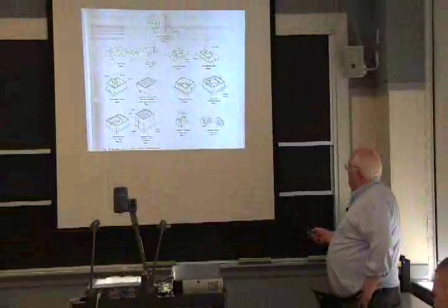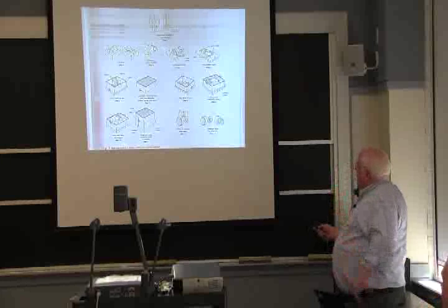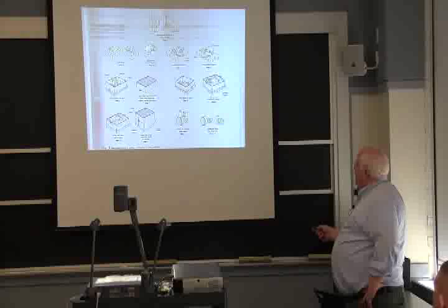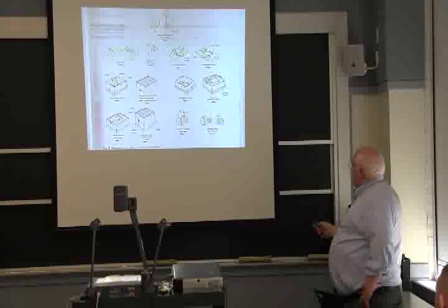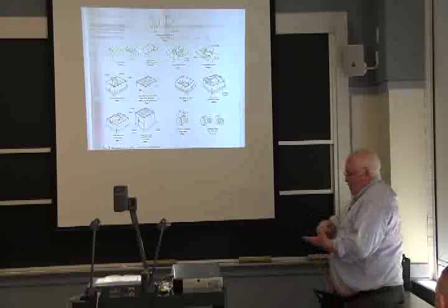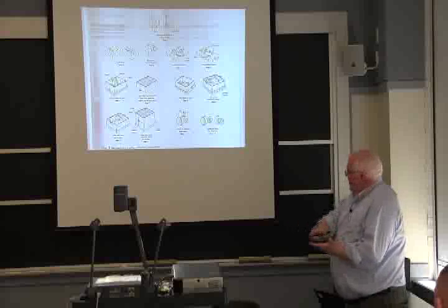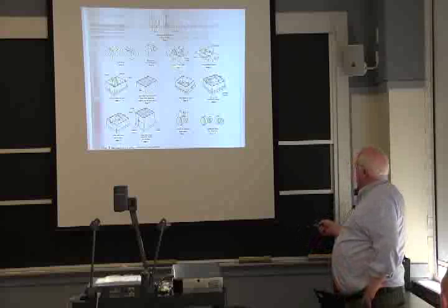That gives you a cavity, or actually what you do is you get the core halves and you might make a wooden part, you might make a metal part that's basically from some of these molds in the core box. You basically then bury this thing in sand, but it's on two layers. You've got a piece of plywood, half here and half here, the cope and the drag.